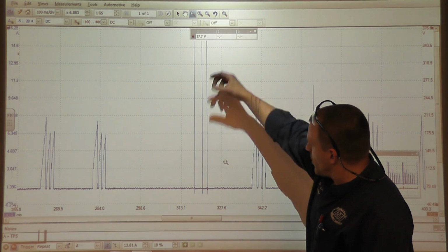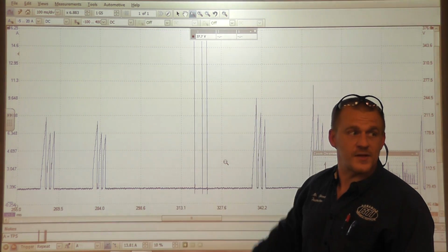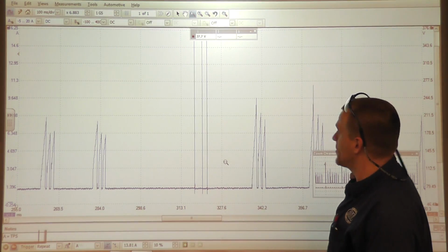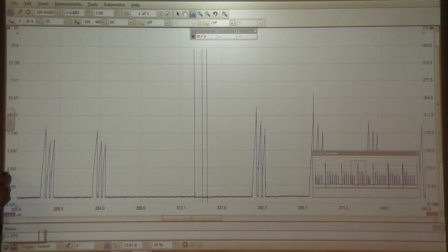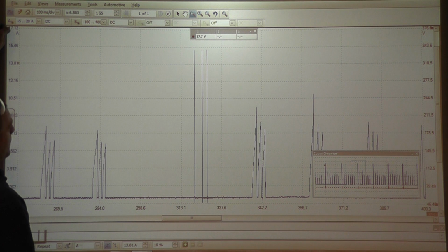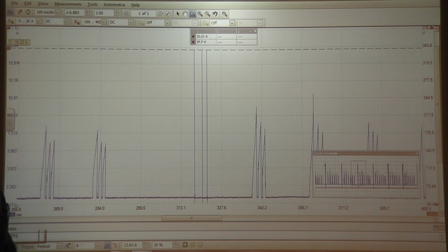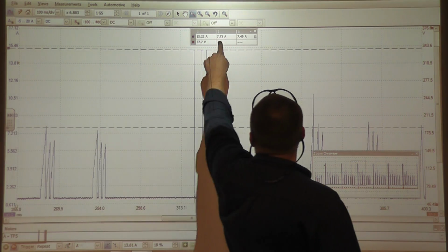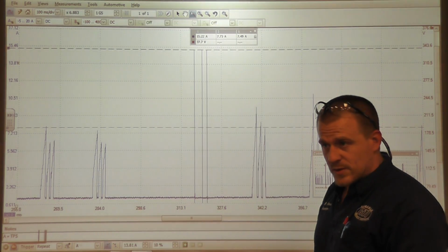Look how high the spikes are and how small the dwell time is. The computer's protecting itself with this right now. That's what's going on in this picture. We have some circuit protection taking place. You take a look at that waveform. We're getting a peak amperage of about 15 amps of current, as opposed to one of our other ones, where we try to get an average of maybe 7.7. So almost double the amperage that this number 6 coil is producing.